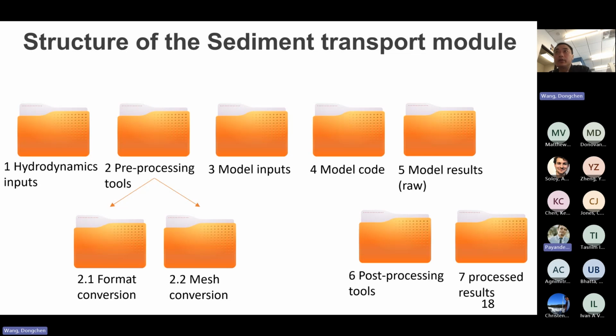For example, we can assume a Rouse profile. If we have the grain size distribution in the vertical column, we can hypothesize a Rouse profile in the water, inversely calculate the settling velocity of the floc, and also estimate the floc size using the difference between the lab data and the in situ LISST data. There are many ways to do this.